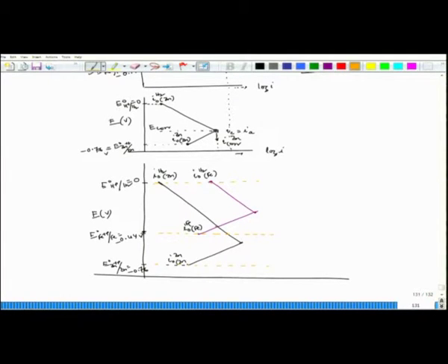As we have known from mixed potential theory, during polarization, whenever a reaction, whether it is a cathodic or anodic polarization, experiences another reduction or oxidation reaction, they should be clubbed or joined or added in order to reach the mixed potential where the net current density should be 0, or total cathodic current density is equal to the total anodic current density.